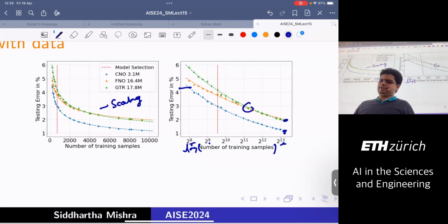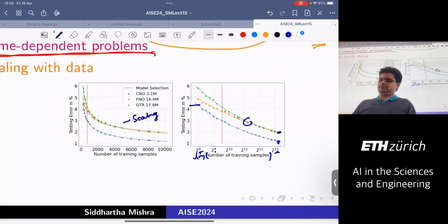But what is interesting is that you see the amount of data that is necessary, right? Because, okay, this is not the hardest problem on earth, but even to get 1% error here, whatever 1% means, some number that we fix, some desired level of accuracy, you see that we need about 8,000 samples. And this is expensive, right? Each of these is a CFD simulation. It takes some time. We have very fast code, so this can be done fast, but in reality, you don't have that advantage, right? So each simulation can take, let's say, 10 minutes in 2D. And then you have 8,000 of these.